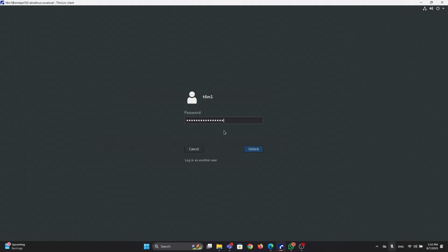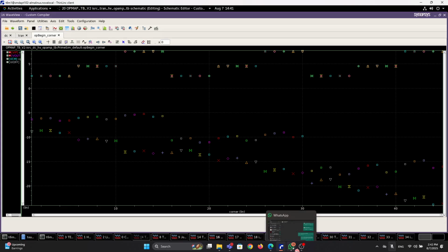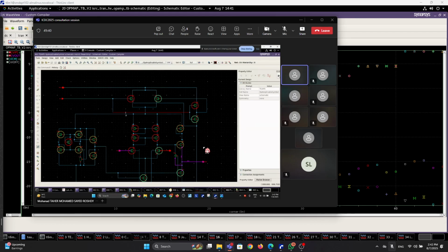Oh, yeah. So you mean like VDD from here, or from here, after when we have the enable? It should be from here. You need to ensure this is very close to 9 volt. If VDD A is 9, after enable, this should be around 9.